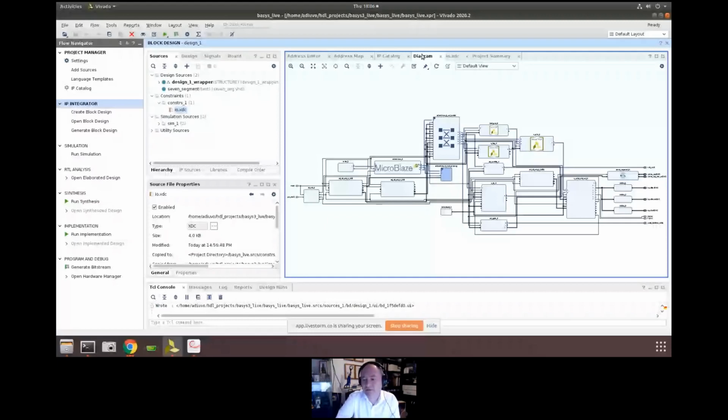So someone was just asking if I show the generation of the platform interfaces in the next lab. Actually, no, because we're not doing any. We're just going to use the embedded flow for this. So we're going to be using the embedded Xilinx flow, not the accelerated flow, because it's an Artix device. It's not an MPSoC or a Zynq or an ACAP device. It's just a standard, normal FPGA. So that accelerated flow is not really suitable. So we'll just be going with the normal embedded development flow in Vitis.